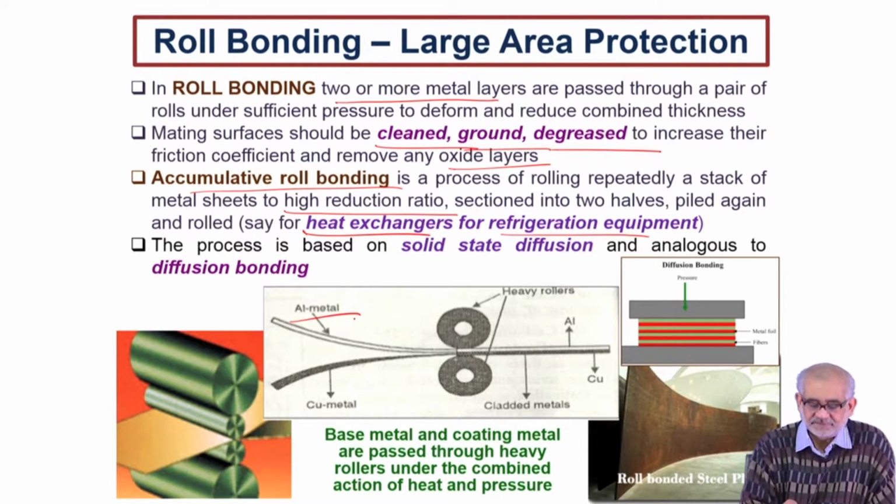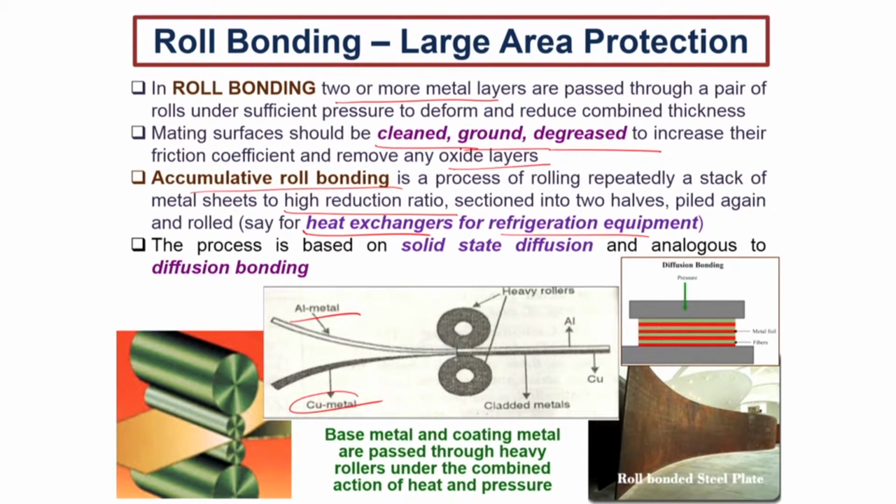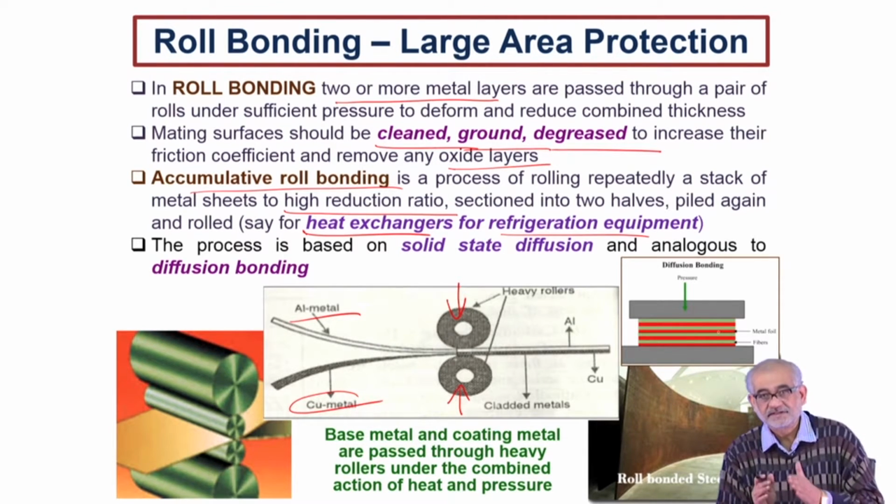So this is the aluminum metal, and this is a copper metal, and this is how you form a clad of aluminum copper through these roll bonding processes. But remember, the pressure we apply is applied only when you are passing through the roll, so it is temporary, transient. You can also do a diffusion bonding process where you have alternate layers of, let's say, a gray and a red metal, two different types of metals, pressed together, with uniform thickness and arranged in some alternate sequence.